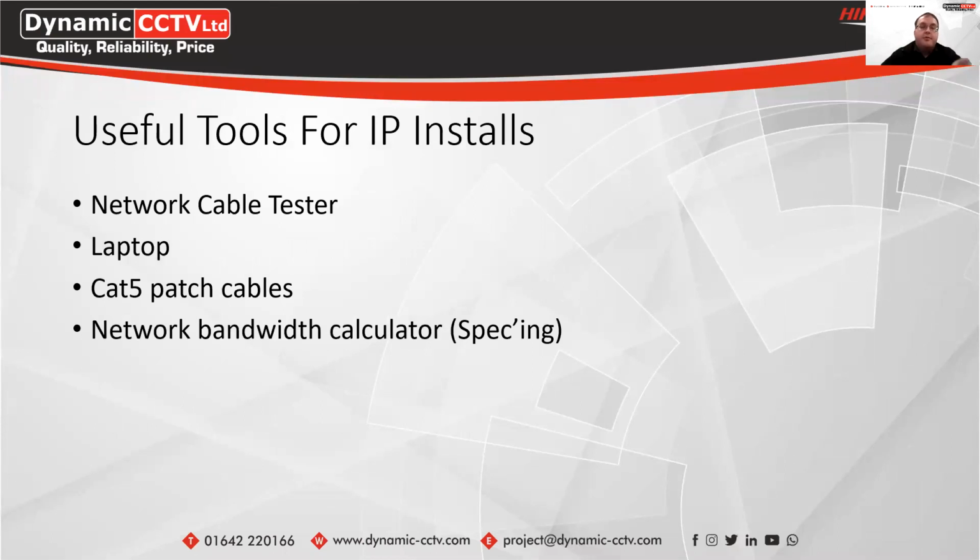So the main tools really for installs, especially for IP installations, is a network cable tester, especially if you're making your own patch leads. I know I've done it a few times where I've got the cores mixed up on the Cat5 crimps. Network cable testers, very easy to use, and will let you know if you've got any of the cords the wrong way around. The most important one of all is to have a laptop with you, even for TVI systems.